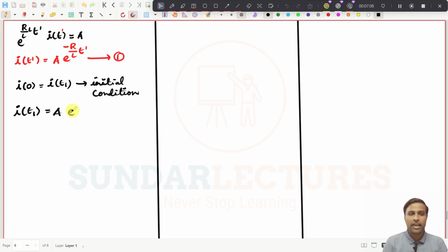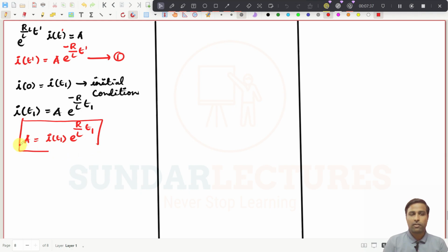So it will be A e power minus R by L, and instead of this t dash, you need to put t1. So if you find what is A here, A can be written as I of t1 into e power, the denominator brought to the numerator, R by L into t1. This is the value of A now. So now I can substitute this A in expression number 1.